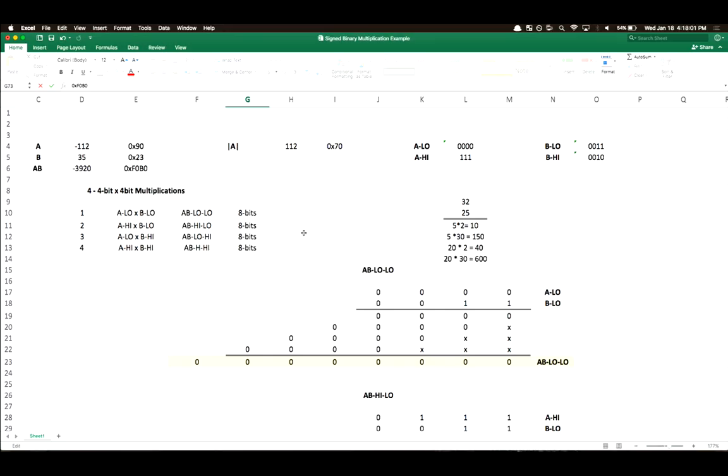But I broke it up into 4-bit by 4-bit. So for your programs, you're going to be breaking up your 16 bits times 16 bits signed into 4 8-bit by 8-bit multiplications if you go with this method. This is just one method. I'm sure if you guys have been to office hours, the other TAs have been showing you other methods where you don't do it this way. You can use 2's complement to do that. And I made another small example to show the other way.